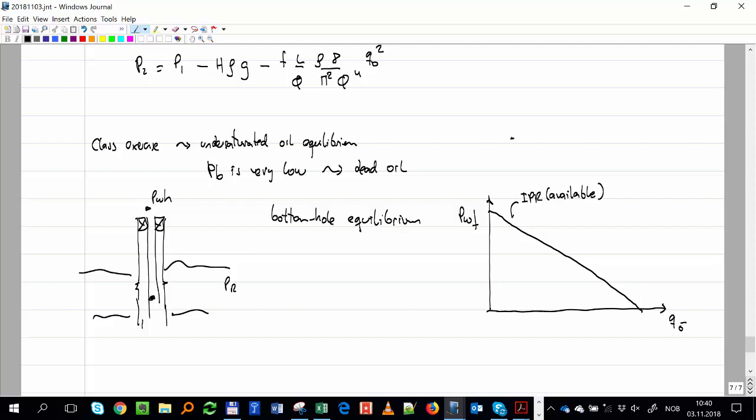Now, the curve when I go from the other boundary, where I have fixed pressure, from here down, that's the counter current, and it's going to look something like that. The required pressure, TPR, at the inlet of the tubing at the bottom hole. Where is the intersection? What is the flow equilibrium? The intersection, right? Just like in the case of gas. That's where my system will be operating.